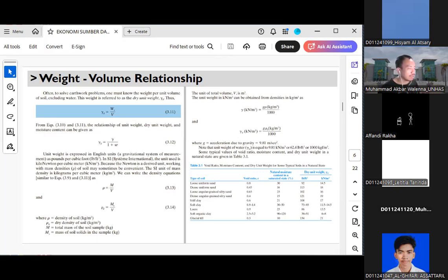We really need to make sure that the clays are competent, but being competent means that the water should be expelled so that we can rely on the weight and the strength that can be exerted from the solid grains of that soil. Okay, that's what I can say.